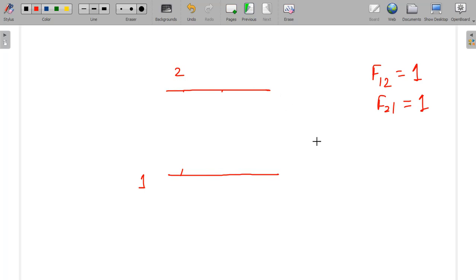In the previous problem we saw that the two plates were finite, so we used the atmosphere as an enclosure for the third participant. But here these plates are given as very large, infinitely long, so that you can consider these assumptions. So for this one, suppose the temperatures T1 and T2 are given, and properties are given, say epsilon 1, epsilon 2, and you have to find out what heat transfer will take place. It's a very simple problem.